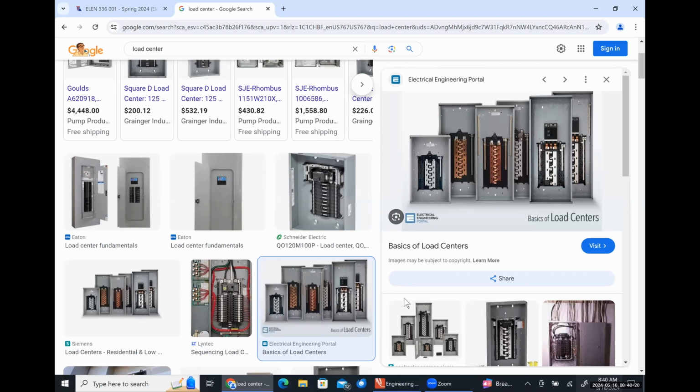Why would you want 240 volts? So your dryer, your electric range, all of those are 240 volt. Usually a hot water heater, 240 volts. Things like lights, small appliances, your microwaves, all that kind of jazz, are 120 volt appliances. What's kind of interesting is this is just how we do it here in the United States. In Europe, everywhere just gets 230. Doesn't matter what the load is, it's just 230. So they don't do this split phase power at all.